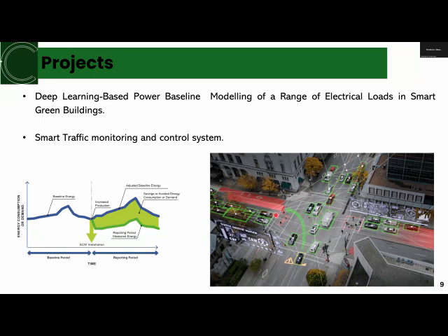A vehicle over here came one minute earlier and it's been staying for a long time. But imagine there are only five vehicles in this line, but there are multiple vehicles on the other line. So we cannot keep this one waiting more than one minute because of only five vehicles in the line. So it needs to check when this vehicle came and how long its waiting time was, right? It sets the green light, and it knows only five vehicles are there. So it sets the green light until these vehicles have moved away and immediately turns it to red. So it adaptively changes the light.